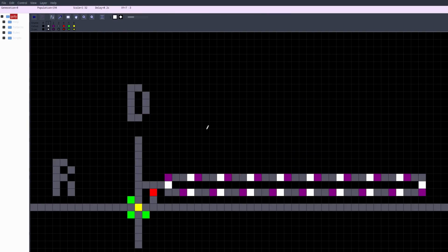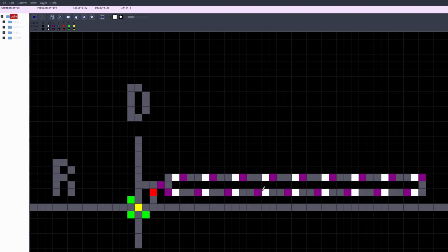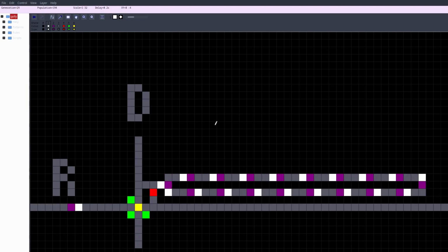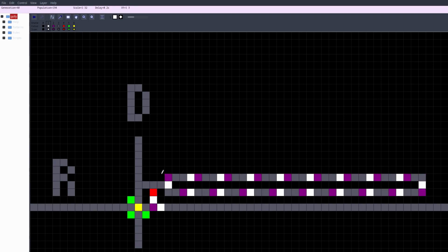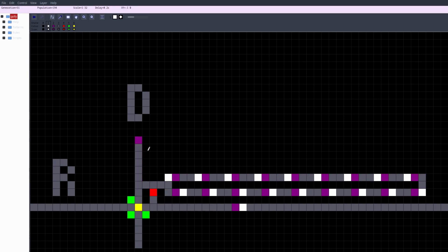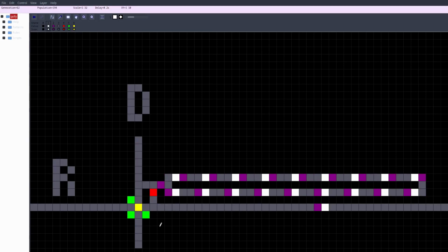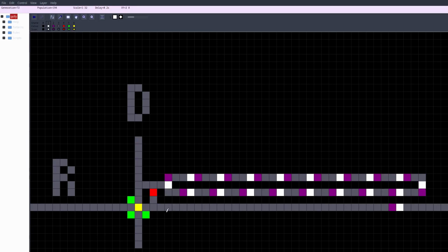This is the memory cell used in the processor's ROM. This loop can hold 18 signals. Each signal is 1 bit. When a signal arrives at the read input, 1 bit is read from the loop and sent to the data output. Notice that this device can be tiled both horizontally and vertically.